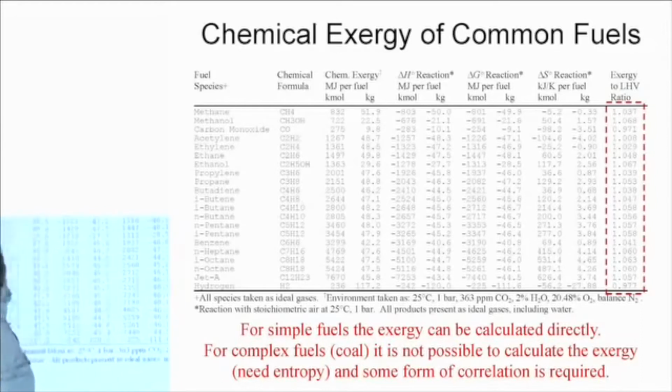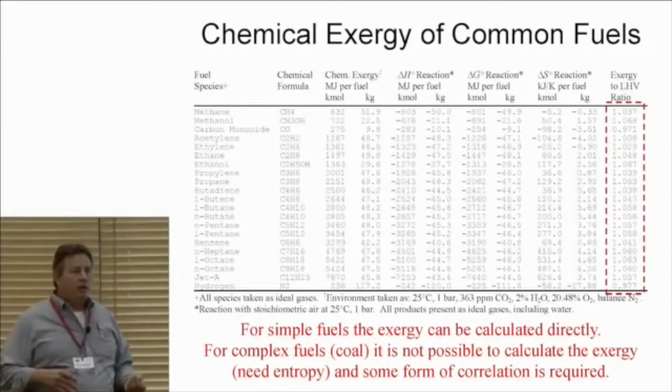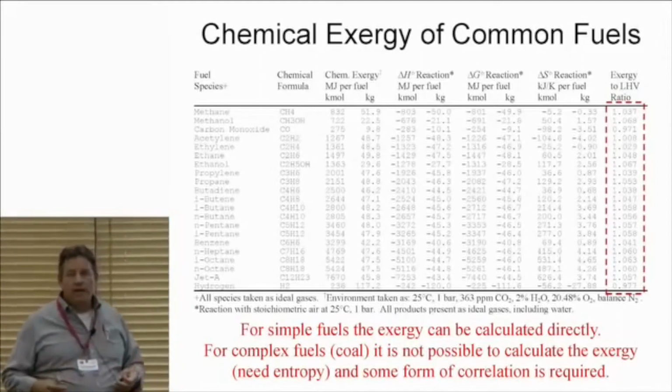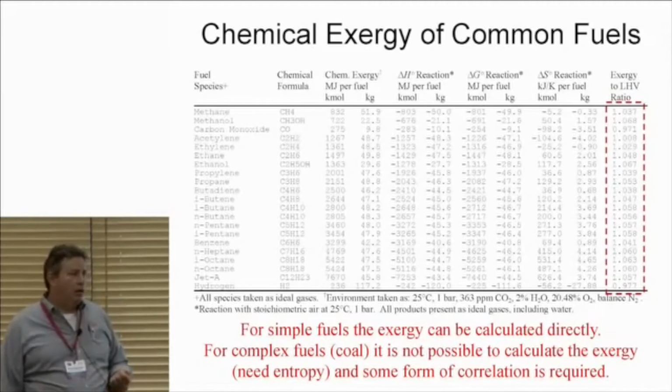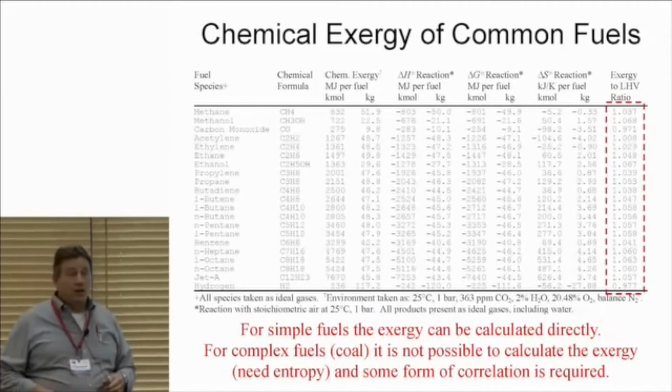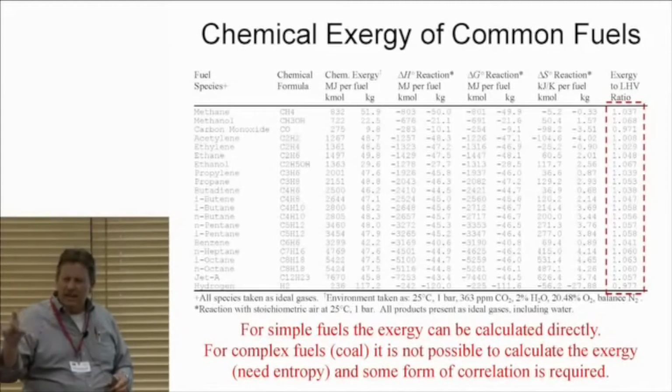Now, if we talk about CO and we talk about hydrogen, 0.97, so a little bit on the other side. But it's not terribly surprising that we haven't had a great failure in the marketplace by using heating values for figuring things out, right? There's a reason why that's been okay. But what I would suggest has not been good is knowing that we evaluate engine efficiency based upon work per unit of heating value, that everybody kind of loses their orientation because they don't really think that's a good comparison to be making. Work per unit of heat, and it's not even heat at the equivalent state that I'm running the engine. So it tends to lead to disorientation about what you should do.